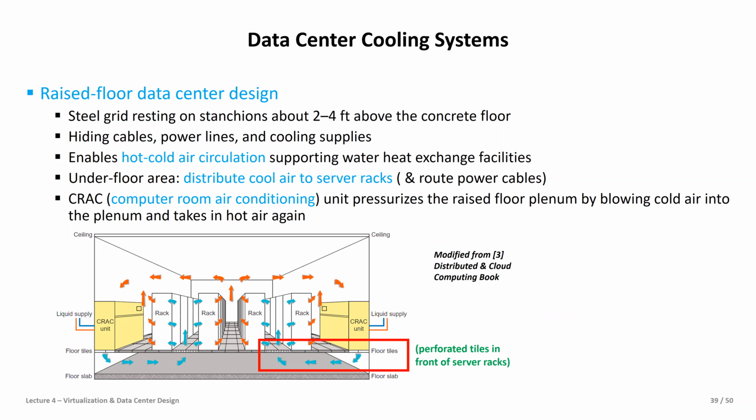could be playing, as in this example, a very important role with the perforated tiles in really enabling the cooling, because of course the cold air comes from the bottom through a so-called CRAC, computer room air conditioning unit. But as we know, the servers will heat it up very quickly, and at the top of the floor it will be hot again, and then it will be sucked in again into this air conditioning mechanism.